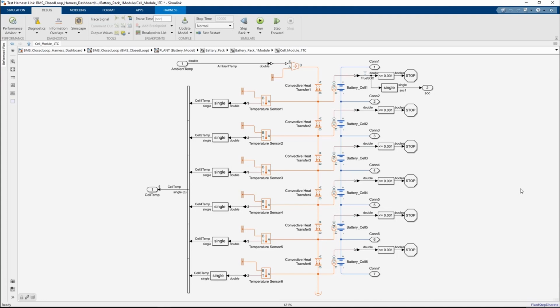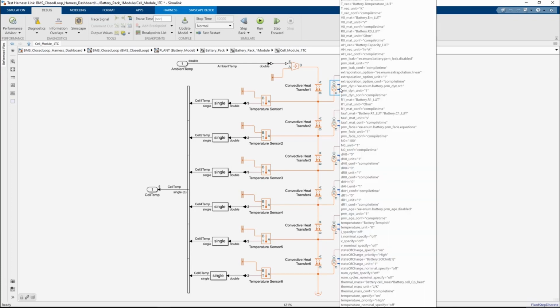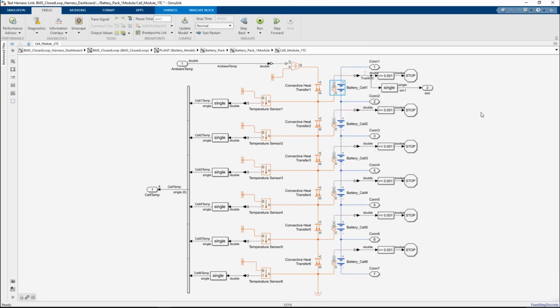The thermal layout is asymmetrical, with cell number 6 at the bottom insulated on one side, so no heat can dissipate in that direction. And cell number 1 at the top exposed to the outside atmosphere and therefore can get rid of the heat by convection. This asymmetry will be responsible for a significant temperature difference among the 6 cells.